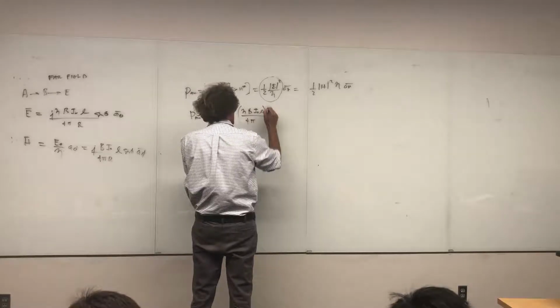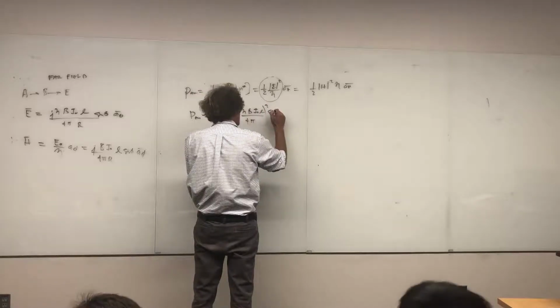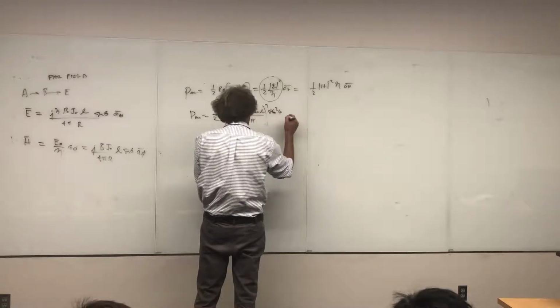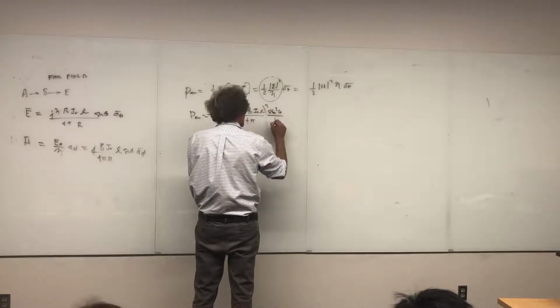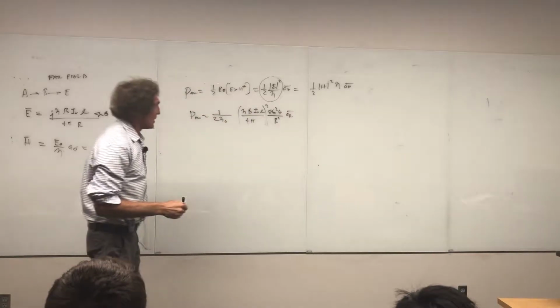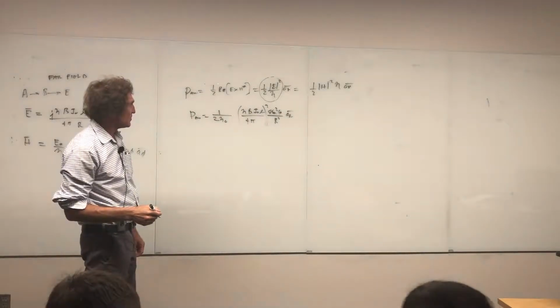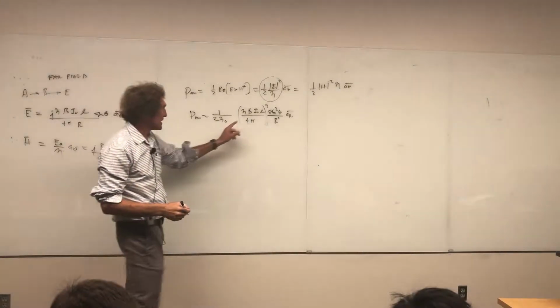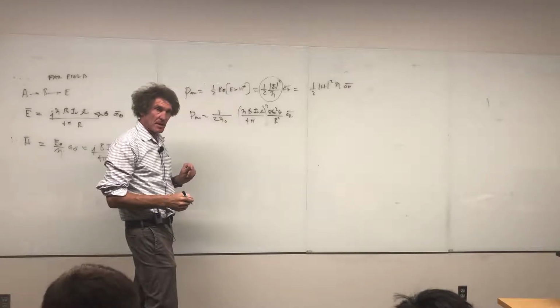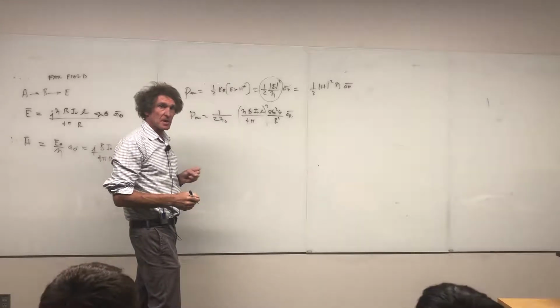Time all that squared, sine squared of theta, divided by r squared, and it's in the a_r direction. Now, that would be the power density. One thing you're going to see is the eta naught here will cancel one of these etas, so you're left with just one eta up top. But that's fundamentally it. Follow me, class?